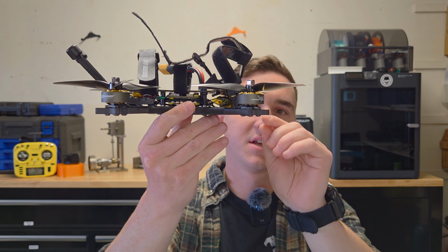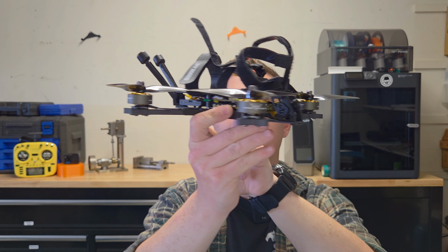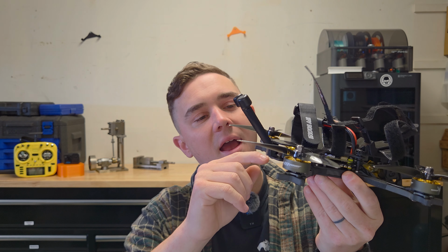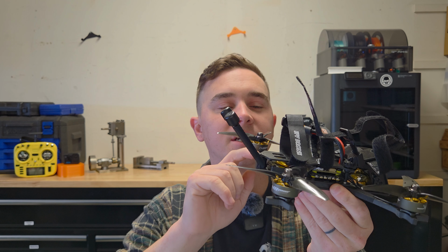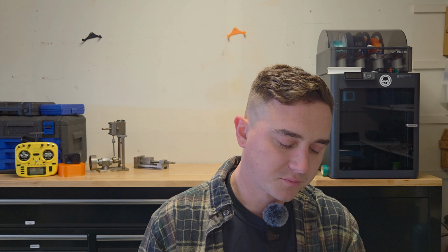Okay. For HD, this is a Walksnail. This is a camera where the wire goes directly to the video transmit system, which is this thing in the back here, with these antennas. And the only interaction that I have with the flight controller is just the video transmit system power, because the power goes from ESC to the flight controller to the 10-volt pad to the video transmit system, as well as some controls. Okay? But generally it's self-contained.